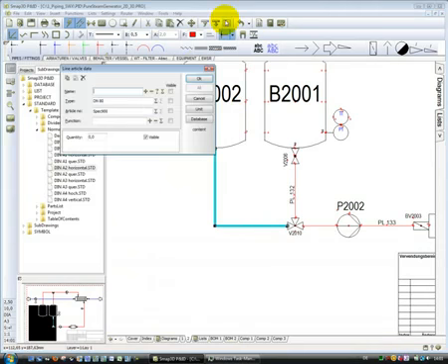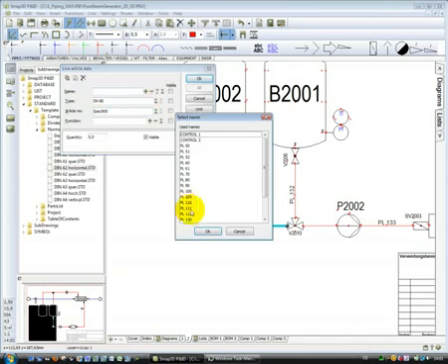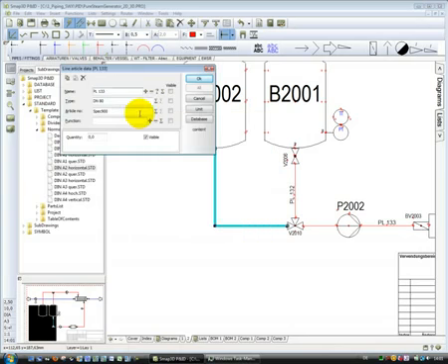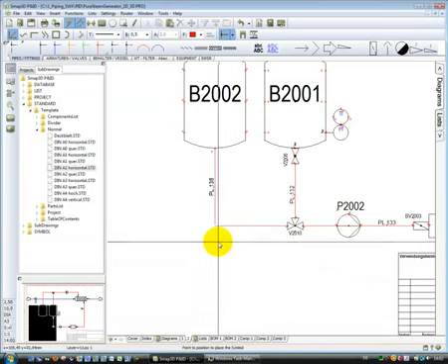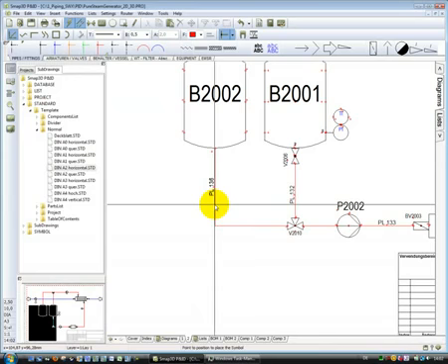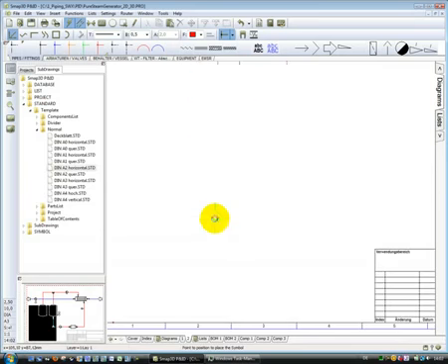And with the connection to the object data, I have access to the assigned information, and I can also define my new pipeline tag for this. Here I use my existing numbering syntax and count up to the next free number, 136. And with this I place this number, and all additional information is available with the pipeline.